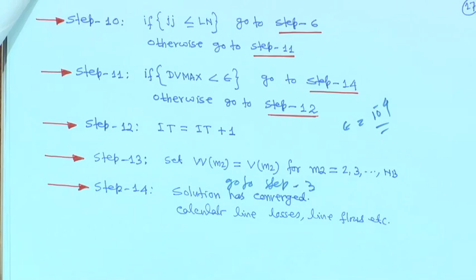Till now, look, the first thing is there is no derivative involved, as happens in the Newton-Raphson load flow method. No derivative is there, and it is straightforward, only that you are exploiting the radiality of the network. The second thing is that if you use a general load flow for a distribution system, you have to go for the coupled Newton-Raphson method.